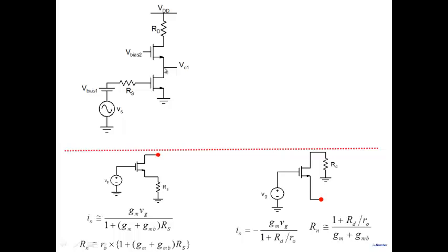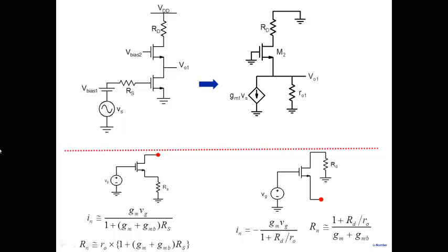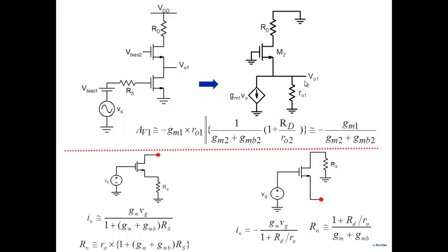That's why I'm calling this some voltage V01. If you want to calculate the gain at this particular point, you build Norton's equivalent at that point. First, note that this whole part that you see here is replaced by GM1 VS and R01, just as before. And this is nothing but coming from here. Now we want to build Norton's current here. I've skipped a lot of points, but let's see if we can understand the steps here.